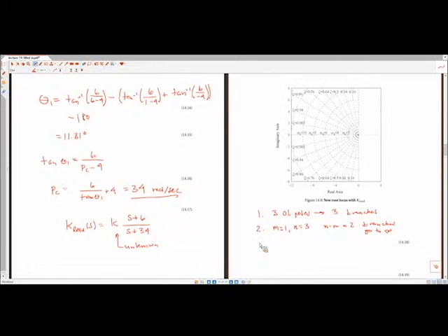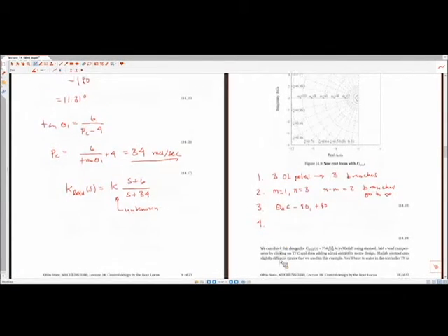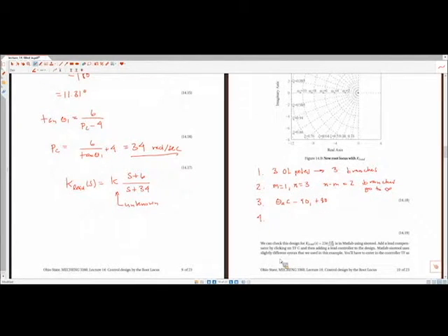Since we haven't changed the difference between these, this is rule 3. That means asymptotes are going to be at negative 90, positive 90, exactly the same calculation we gave for the case of proportional control. And then here's one of the aspects in which this will be different. We're going to look at the asymptote intersection point. We are summing up all the zero locations.